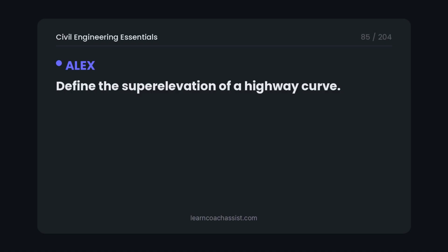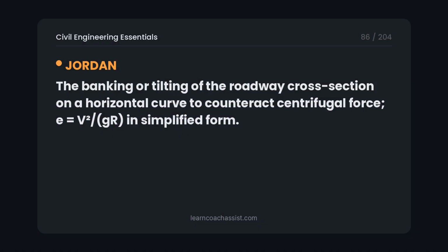Define the superelevation of a highway curve. The banking or tilting of the roadway cross-section on a horizontal curve to counteract centrifugal force. e equals V^2/gR, in simplified form.